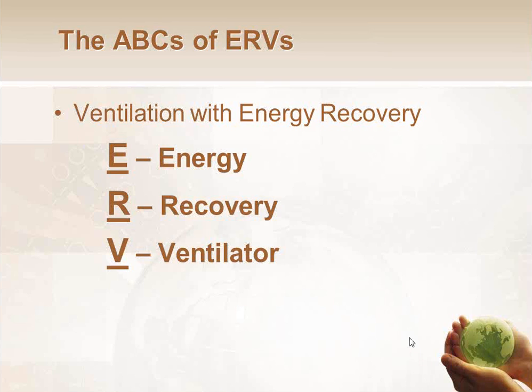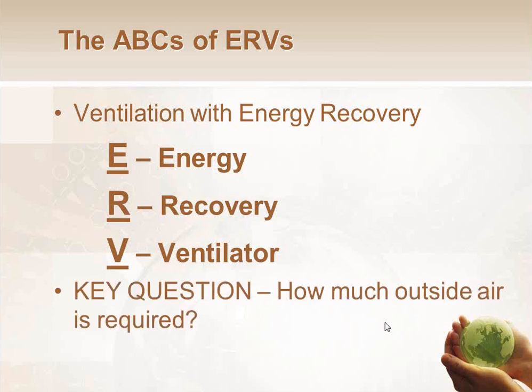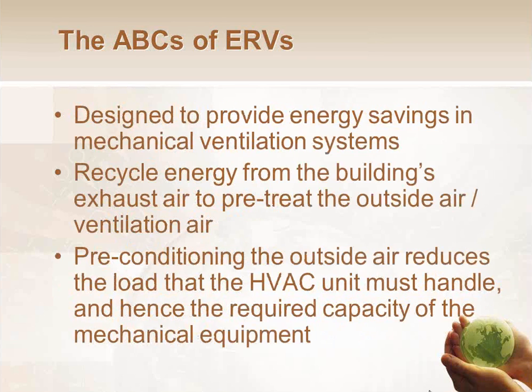The biggest thing on these types of systems is that we have to find out how much outside air we're talking about. If you've got a system that only has 300-400 CFM of outside air, an ERV is not going to be all that exciting of a payback scenario. However, if you've got 30,000 CFM of outside air, it's going to be an absolute no-brainer. So we have to figure out, in between all those ranges, when it makes sense and when it doesn't, from both an economic standpoint and an energy consumption standpoint. That's really what we're going to focus on quite a bit today. So how much outside air are you talking about on your project? That's the first question anyone's going to ask you when you talk about an ERV.